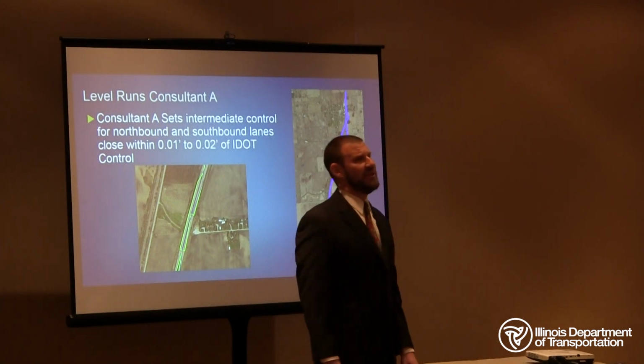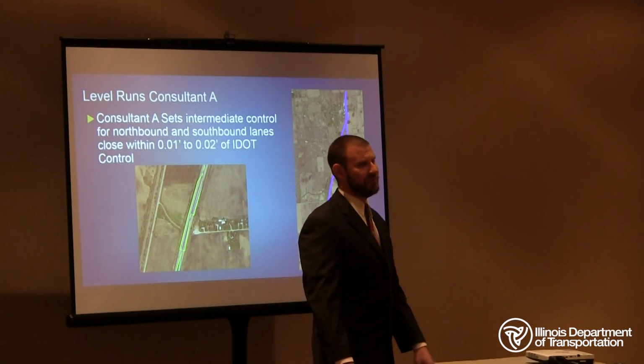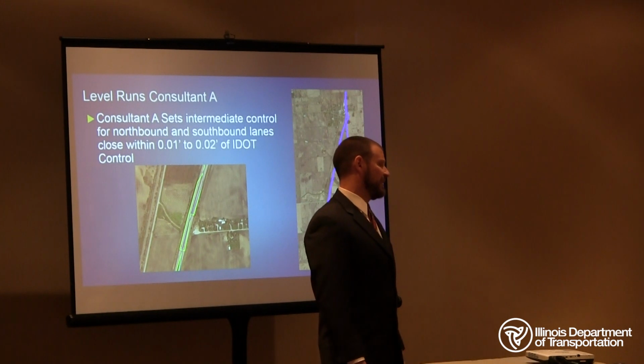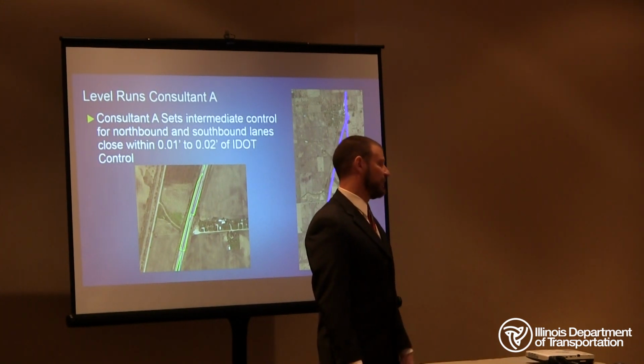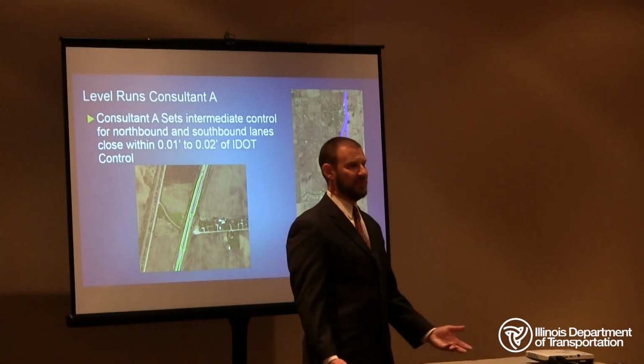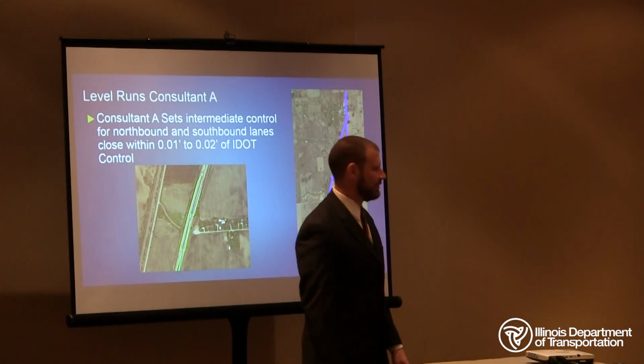So I looked into Consultant A's level runs. They were doing the conventional survey work, and I found that they did things the way we desired for them to do, and they did close within a hundredth or two typically on the bench runs; they closed within a hundredth.